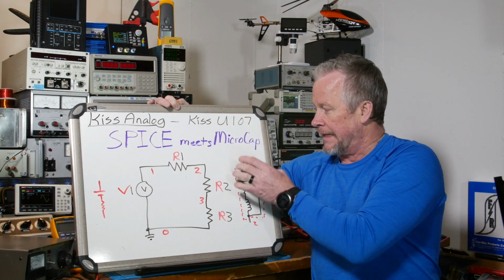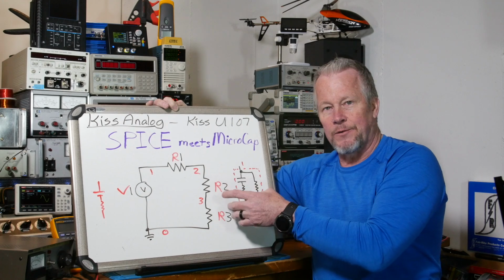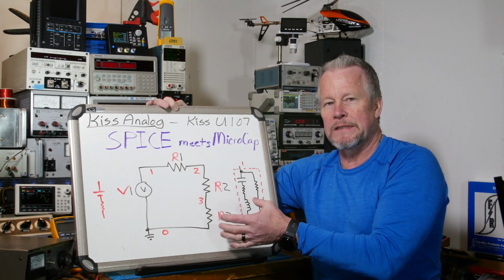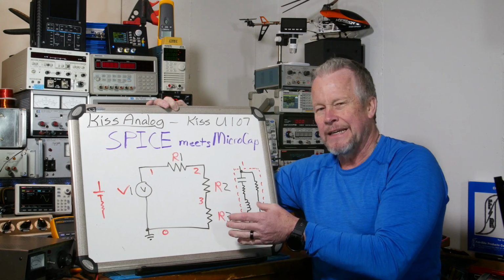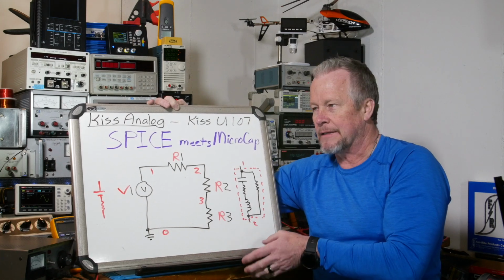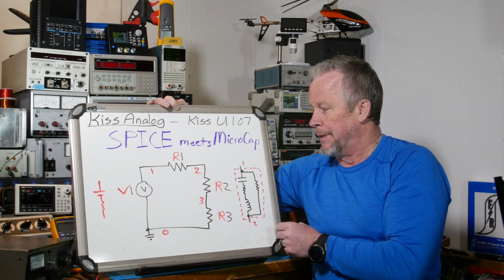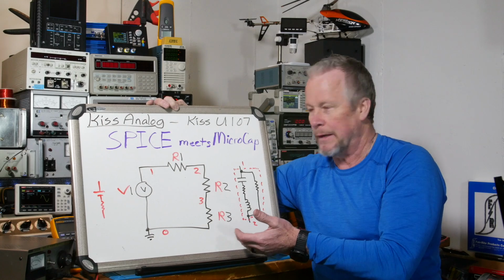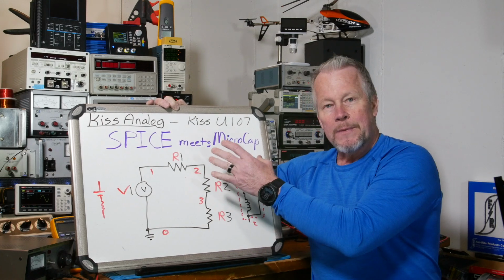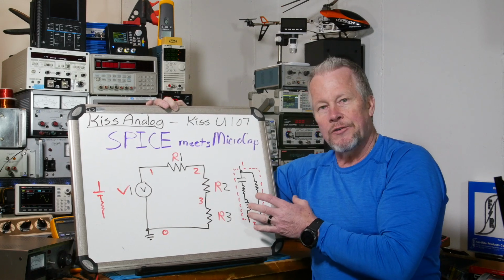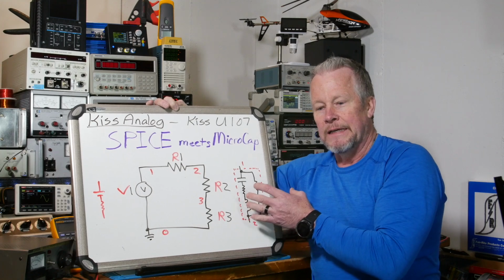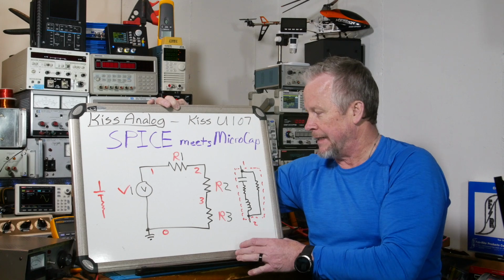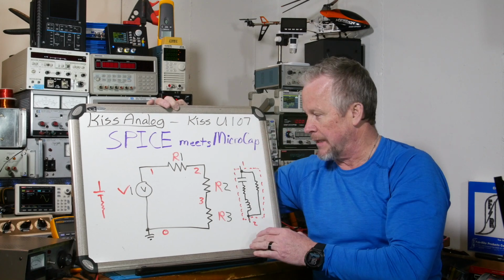Instead of treating it like an ideal part, like a resistor, for instance, it's also going to have some inductance, right? We call some resistors non-inductive resistors, even though there's still some inductance, but much less compared to what they would have otherwise. Anyway, as we enter transistors and all those other things, they get very complex, and there's lots of parameters you can take into account, and that's when those levels come into place.